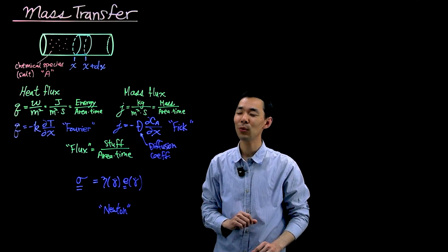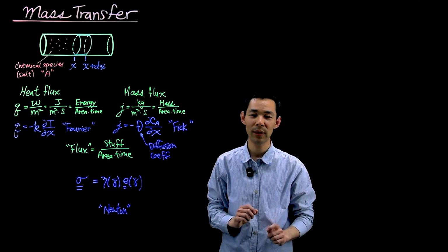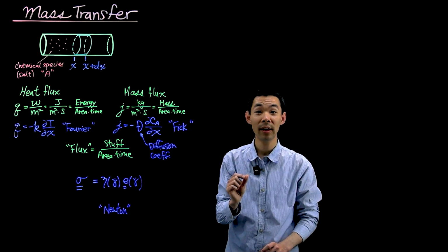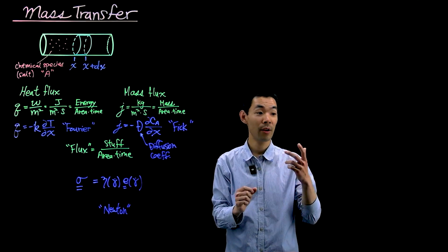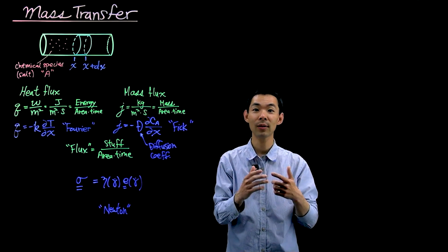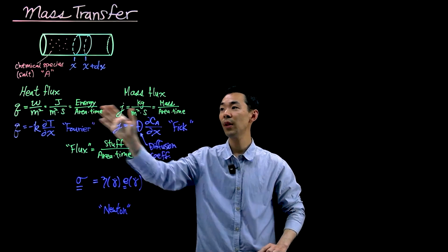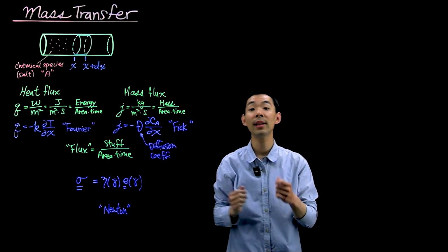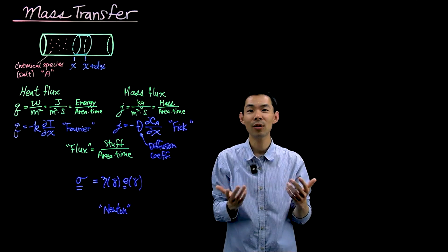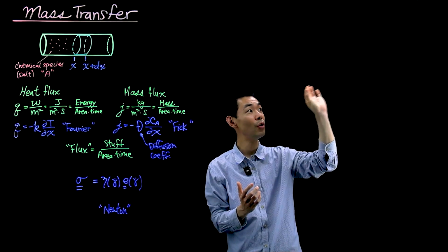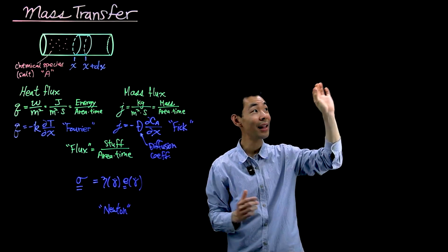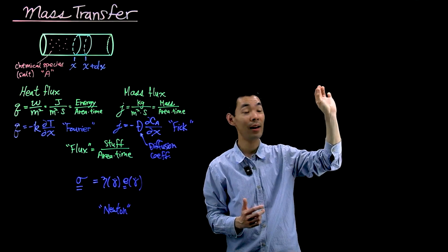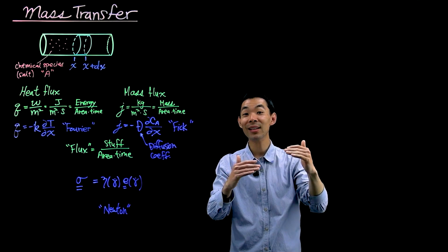Now, fluid mechanics is really hard. It's hard for a number of different reasons. First, generally the function you want to find is a velocity vector, which has 3 components in a 3-dimensional world, x, y, and z. In contrast, for heat flux and mass flux, the species that you're looking for is a concentration, or a temperature. It's a scalar quantity. There's no directionality to temperature. You go to a point, you know the temperature at that point. In fluid mechanics, at that point, there are 3 scalar things emanating from that point. So it's a vector at a particular point, which means that everything gets upgraded by 1.